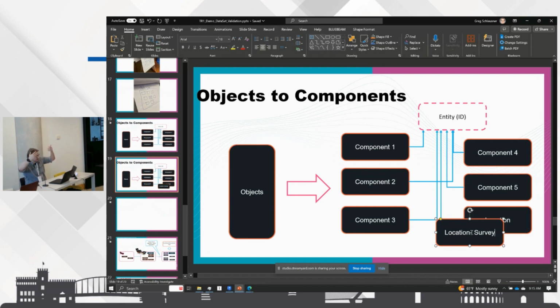Or what would happen today, roughly, is the second you override one of the locations along the alignment, I'm using locations very generically so we don't get caught in the semantics here, you're essentially invalidating all the future points that you have to adjust. This is why having the construction as-built and as-designed at the same time is important, because these are the things we're missing if we don't capture this.